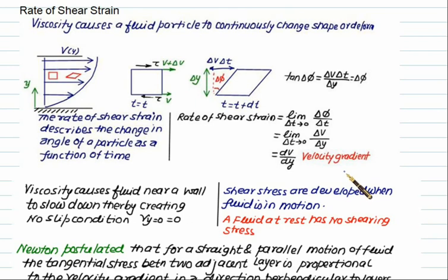Okay, in the introduction chapter of fluid mechanics, we have to deal with Newton's law of viscosity, which is given as tau is equal to mu into du by dy, where du by dy is called the rate of shear strain. Initially we have a fluid element in a rectangular shape, and because of the no slip condition, the fluid at the wall has zero velocity and the velocity goes on increasing. Finally, this velocity is a function of y, as the y direction is shown upward.